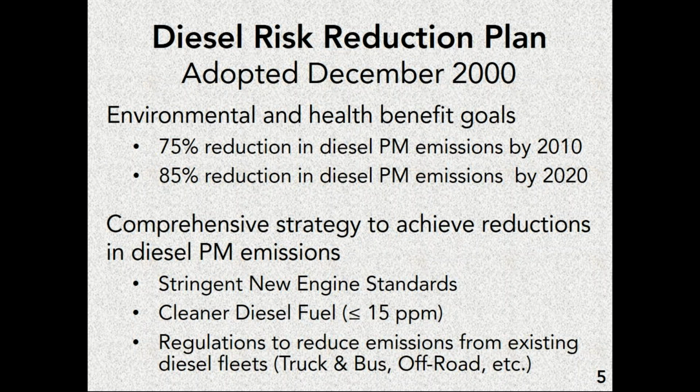Number one, it doesn't burn very well, and anything in the fuel that doesn't burn very well is going to turn into particulate matter. So the more sulfur you have in diesel fuel, the higher the particulate load coming from that engine. So automatically, if we want to reduce the particulate matter load, we want to reduce sulfur to get there.